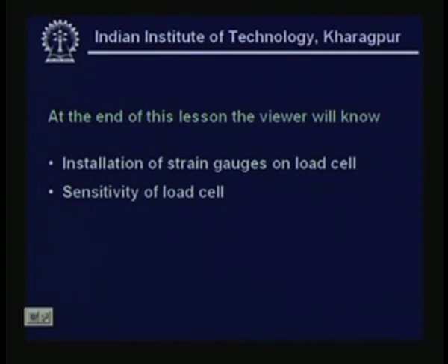Sensitivity of the load cell, in both cases, in the case of column type load cells as well as in the cantilever beam type load cells, we will compute the sensitivity of the load cell. Sensitivity means the load cell as well as the Wheatstone bridge combination, because ultimately we will measure this unbalanced voltage by means of the Wheatstone bridge, and that unbalanced voltage will be calibrated in terms of load.